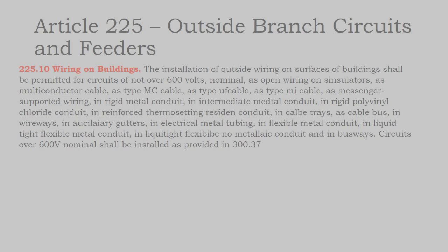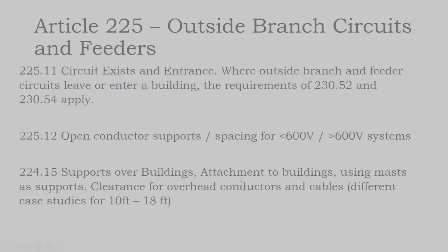You can have wire in metal conduit, wire in PVC conduit, wire in cable trays, and even certain cables that we'll get into in section 300 have protection and support built into them. And so if you see just a random cable running up the edge of a building, either it's the system ground, or it's a special cable that probably has a harder shell around the exterior of it.